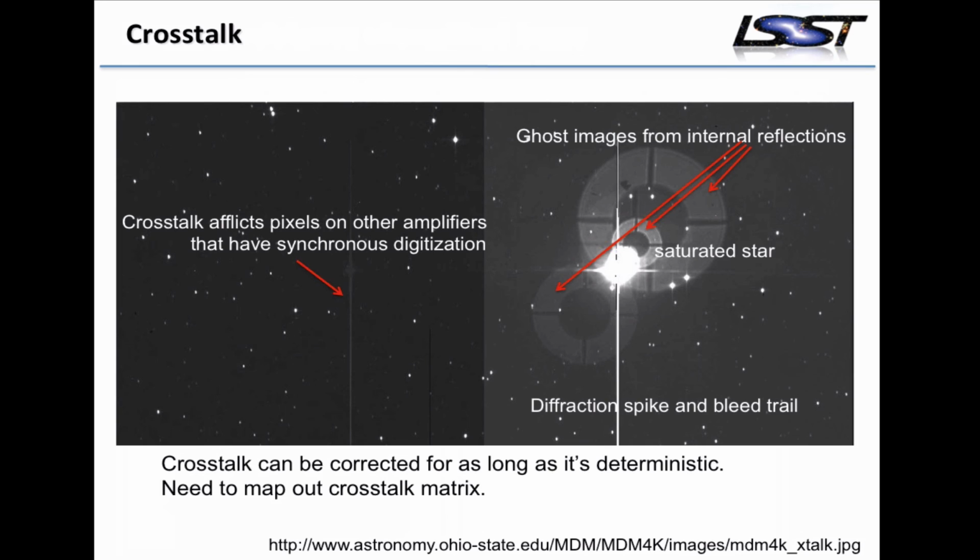Another example that doesn't show up so clearly on the projector screen, but is better on the laptop, is that there can be capacitive coupling between adjacent amplifiers, so that when this signal on the right-hand side reads a really bright signal level, you can just barely see a ghost vertical band on this left-hand side that's much clearer on my laptop screen than it is on the screen that you see.